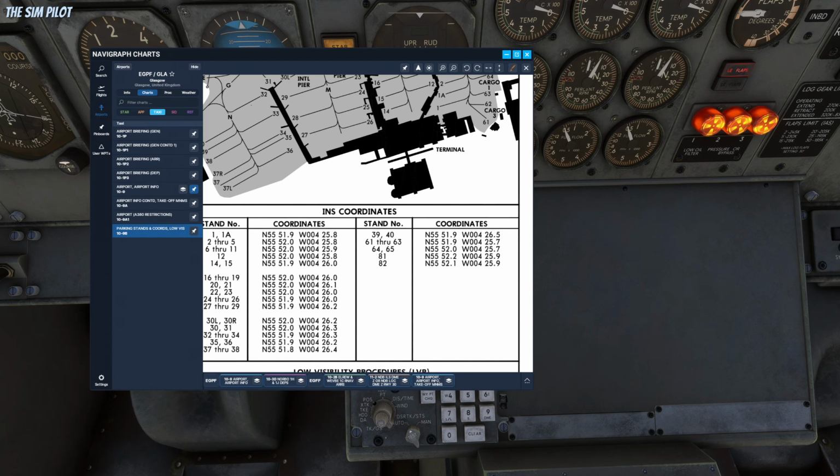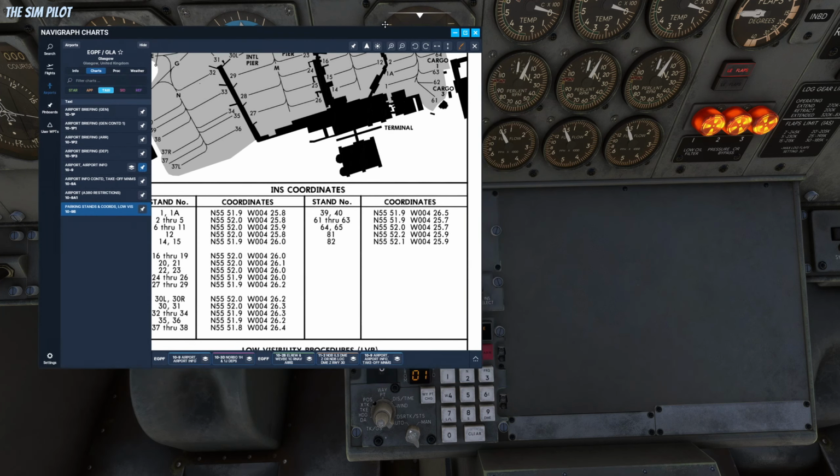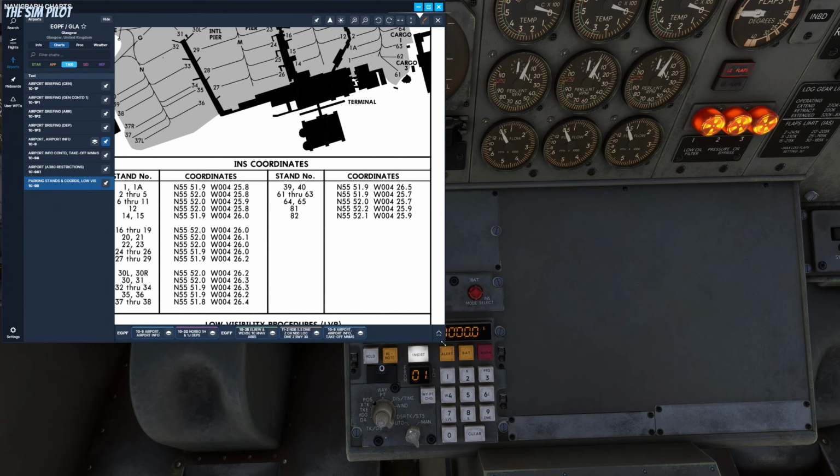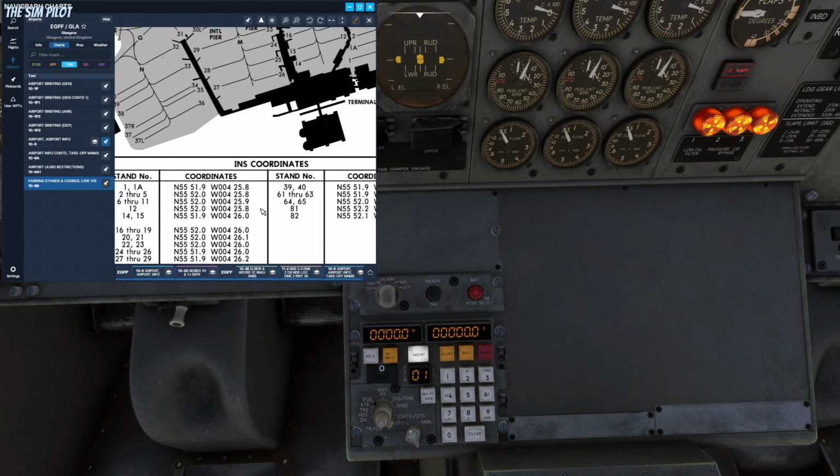Little Navmap was 5551, this is giving 5552. That's close enough. Actually 5551.5, because the seconds is the decimal point. Just know that in Little Navmap the decimal point is your seconds, so don't get confused. And then 425, 41, 425.7. So that's also really close. So you can use those coordinates to align your INS if you don't have Navigraph. So that's another way of doing this.